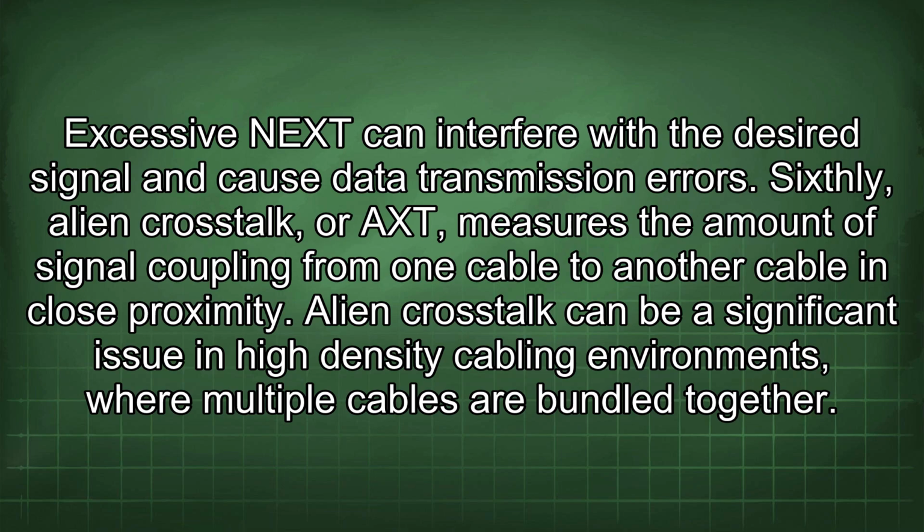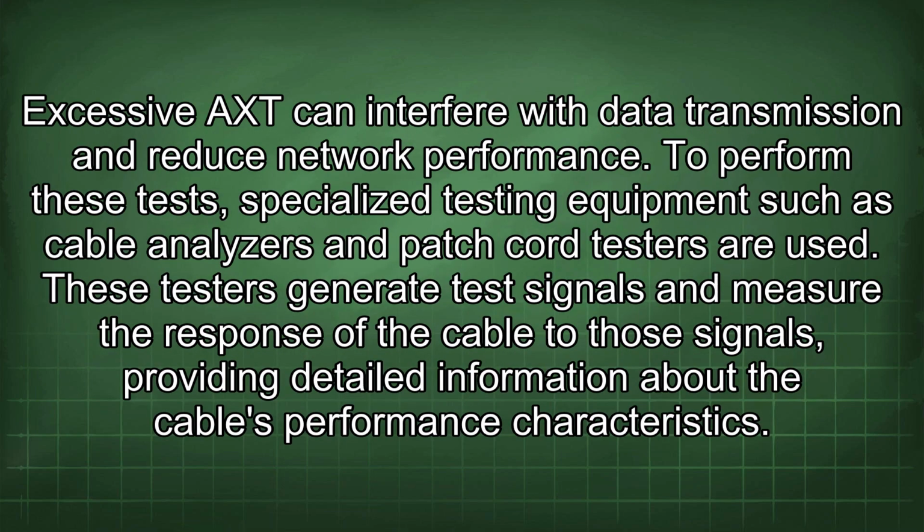Sixthly, alien crosstalk, or AXT, measures the amount of signal coupling from one cable to another cable in close proximity. Alien crosstalk can be a significant issue in high-density cabling environments where multiple cables are bundled together. Excessive AXT can interfere with data transmission and reduce network performance.